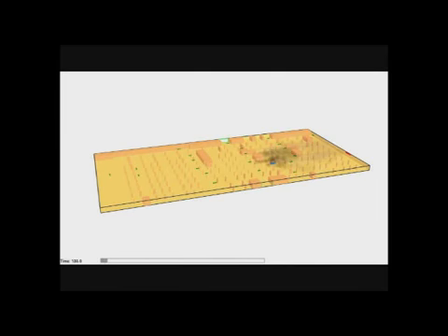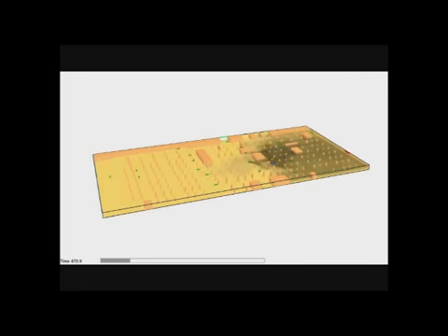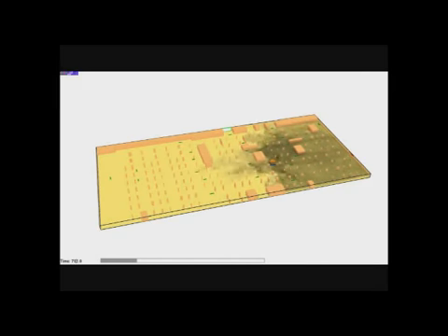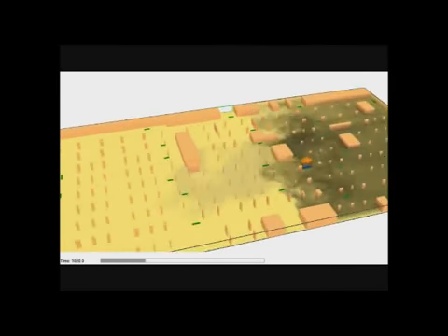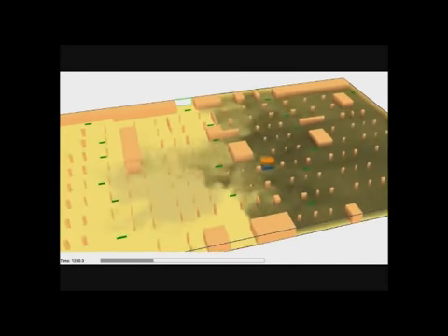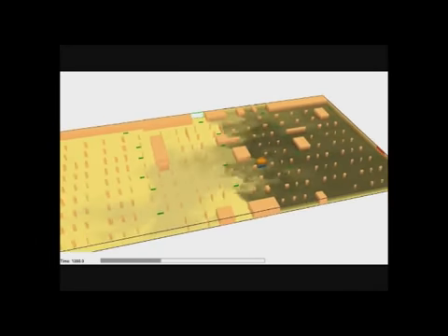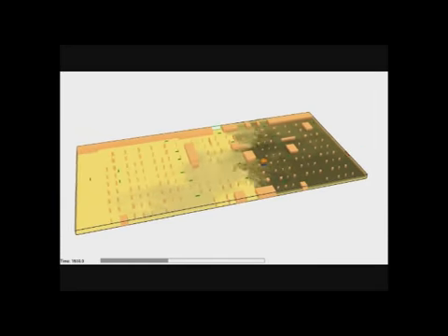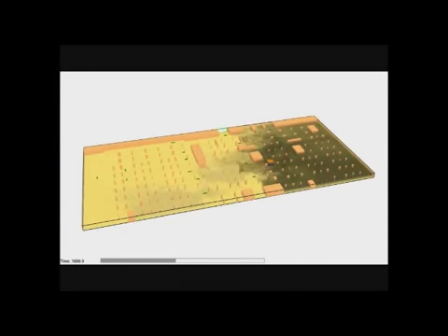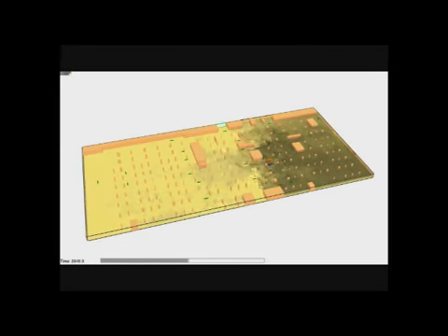Here you see very good compartmentalization, or zones, defined in this car parking area using these jet fans. These jet fans are able to keep the smoke and fire constrained to this zone only. So there is not much smoke going elsewhere, and this is also very light smoke, so it doesn't matter because visibility is good in this complete area. So the whole of the smoke is mostly constrained. This is also a reasonably large fire. 3.1 megawatts is the fire intensity, which is standard and also specified in standards.